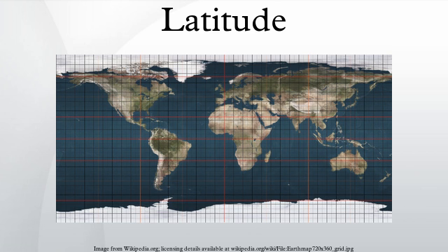Using the rectifying latitude to define a latitude on a sphere of radius A defines a projection from the ellipsoid to the sphere such that all meridians have true length and uniform scale. The sphere may then be projected to the plane with an equirectangular projection to give a double projection from the ellipsoid to the plane such that all meridians have true length and uniform meridian scale. An example of the use of the rectifying latitude is the equidistant conic projection. The rectifying latitude is also of great importance in the construction of the transverse Mercator projection.